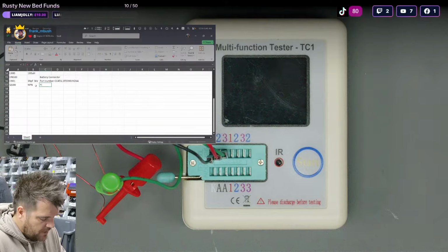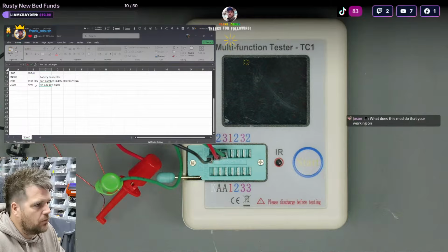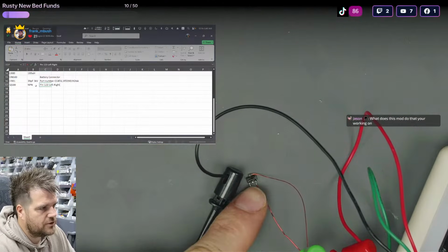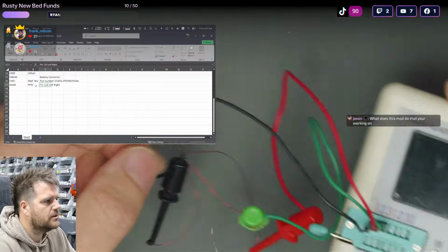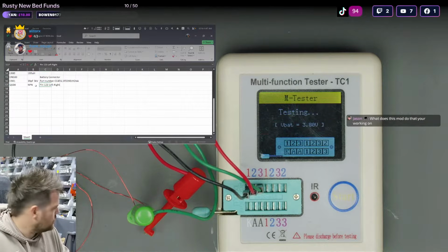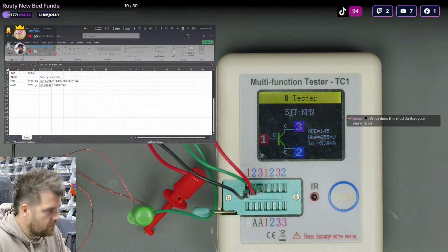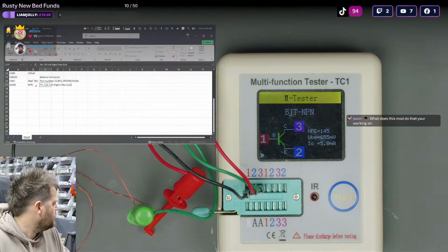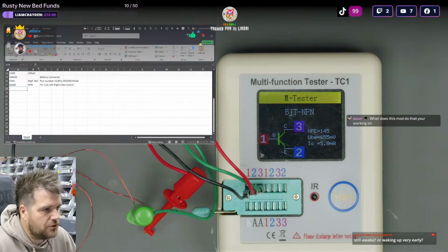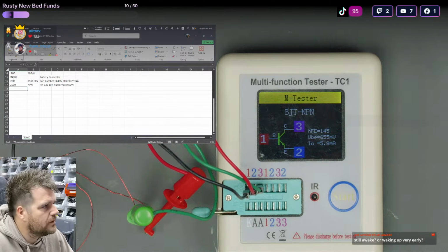In the notes we want pin 1, 2, 3, left to right. And we'll know that because looking at a chip, I would naturally look at the chip in this orientation, so I don't need to write down what that is. And then if we tab across now, we can then put after it. The only important thing here is the voltage from base to emitter is 0.65 volt. That's all that matters for sourcing this NPN, and what I'll do is spec it way above spec anyway. So that's now one done.